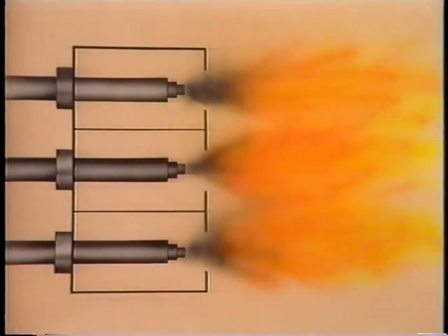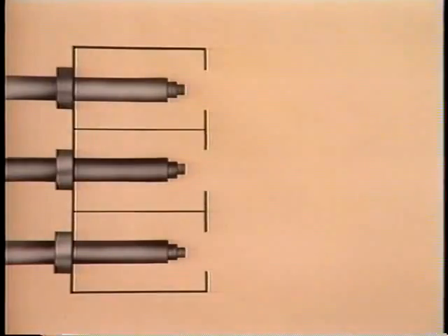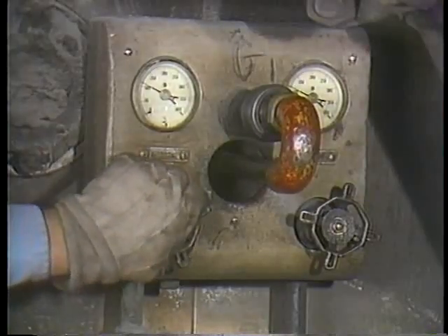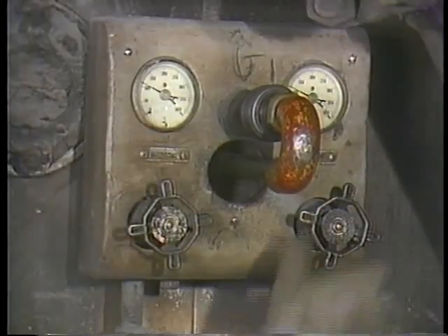If fuel flow to one burner is interrupted and the flame goes out, it may cause a loss of flame from other burners. In this example, if the middle burner flames out, it can't help support combustion on the top burner or the bottom burner. The result may be that the top burner and bottom burner also go out. In situations where coal is difficult to burn, lighting off igniters or warm-up burners can be used to assist the combustion process. Using additional igniters or warm-up burners is a typical approach to avoiding a loss of flame, especially when there is a potential for the flow of fuel to be interrupted.